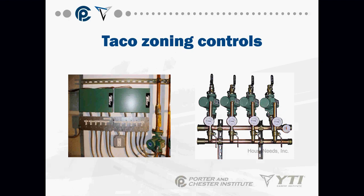The circulator is doing nothing more than providing water flow through the circuit. The zone valve is only opening to allow X amount of water and X amount of heat into that space so that I can heat it. So energy efficiency kind of comes into play depending on the type of piping configuration that you're dealing with.